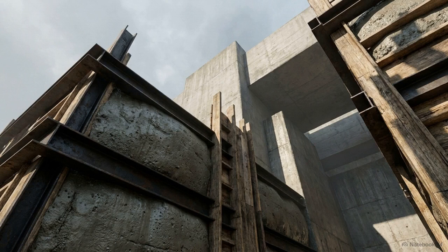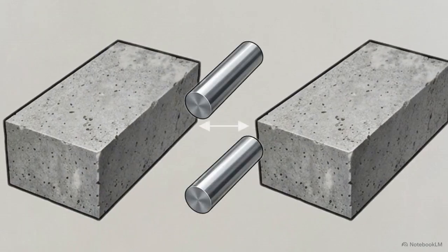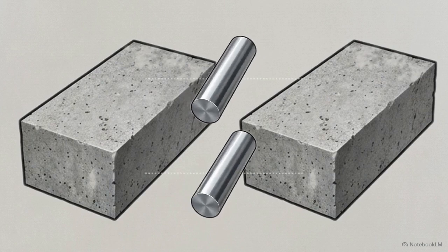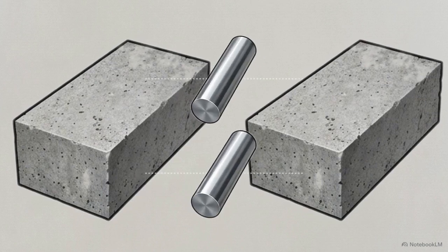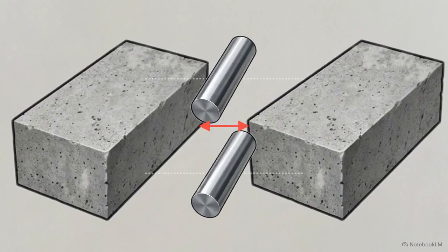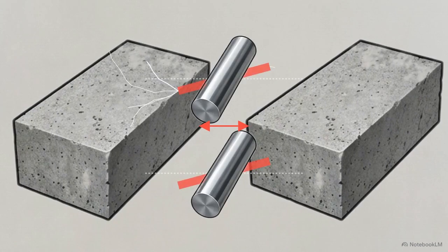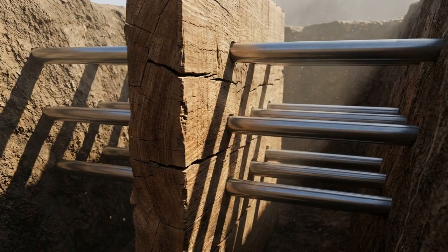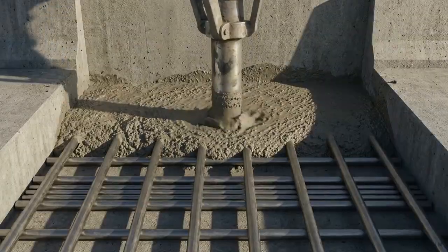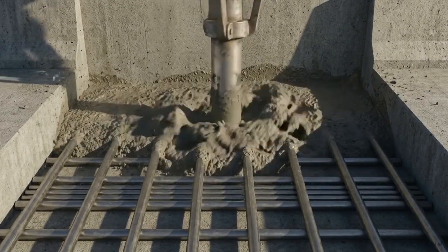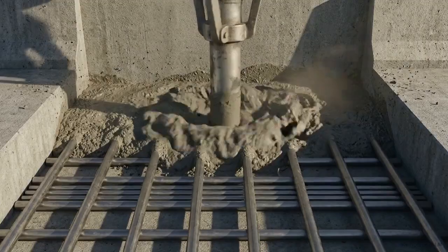Translating this theoretical perfection into reality requires extreme precision on the job site against the sheer physical weight of curing concrete. A millimeter of error in dowel placement carries catastrophic risk. If smooth bars aren't perfectly parallel to the center line, they act as anchors. They lock the joint, prevent thermal slip, and shatter the concrete from the inside out. To prevent this, contractors use rigid hardwood bulkheads or deep metal channel covers to physically lock the dowel bars in perfect parallel alignment, resisting the violent dislodging forces of the internal vibrators during the concrete pour.